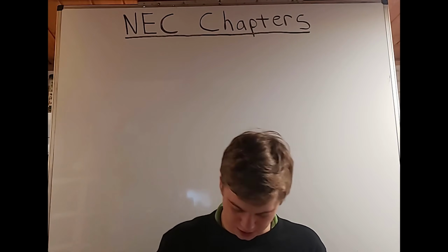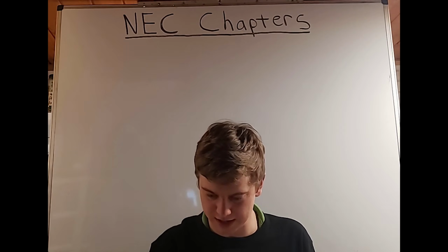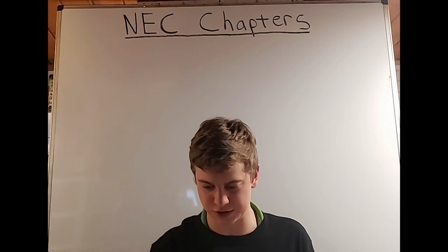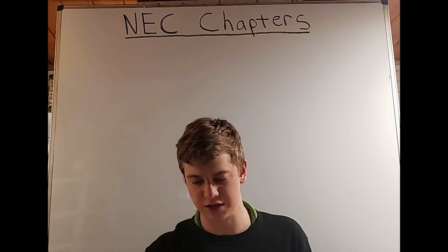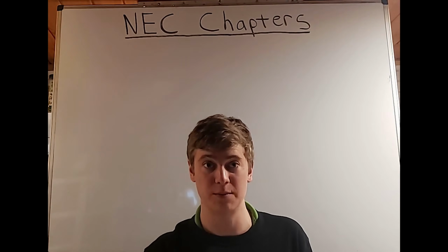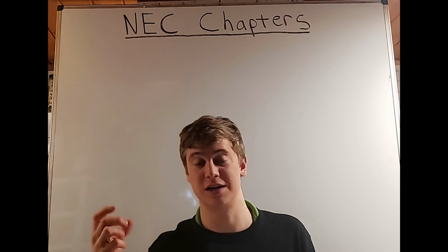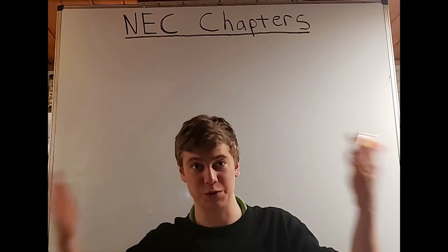Okay, and moving on to 210.18, rating. It talks about the rating for other than individual branch circuits and that they shall be 15, 20, 30, 40, and 50 amperes. Okay, so those are your usual branch circuits, otherwise thought of as your circuit breakers that are going to give you your branch circuits.